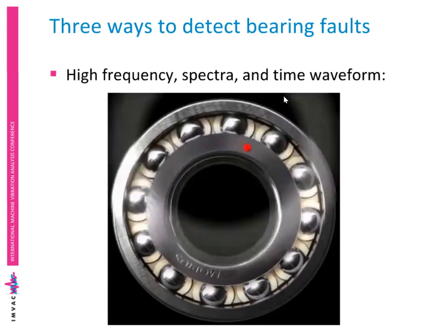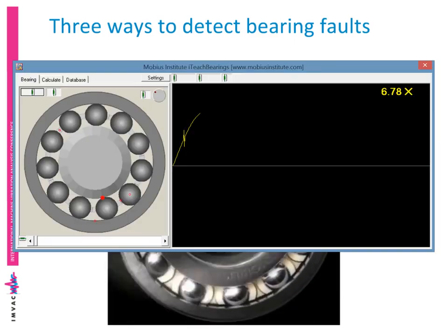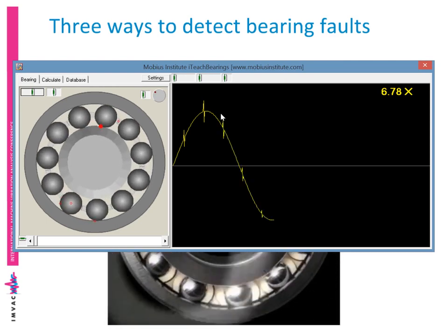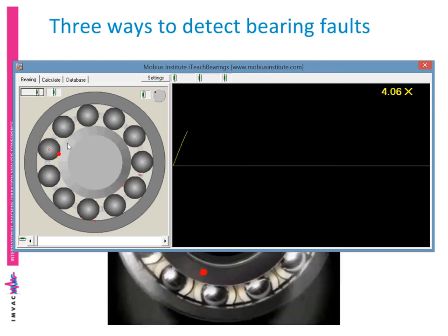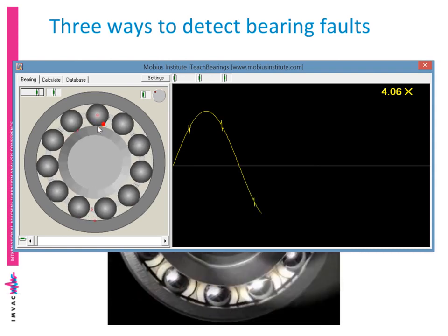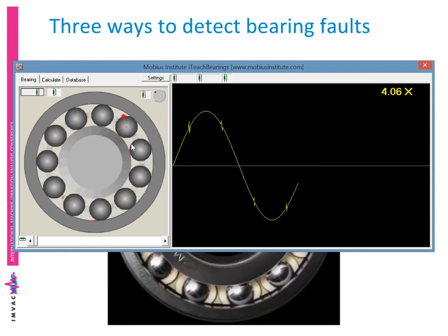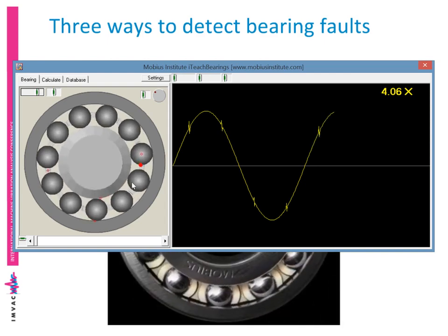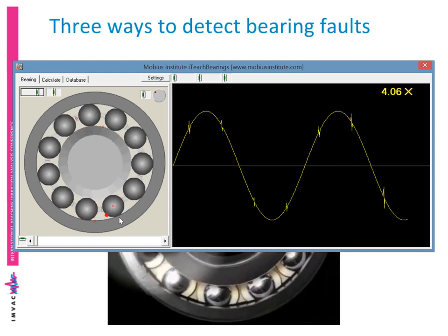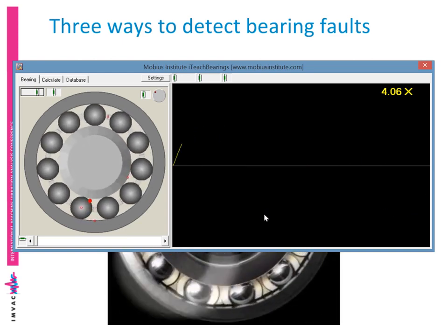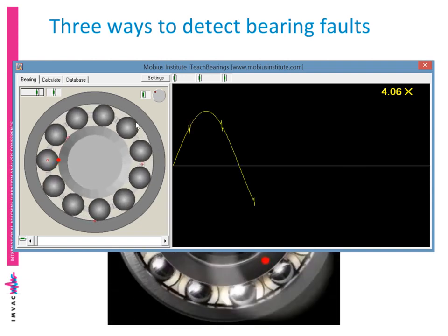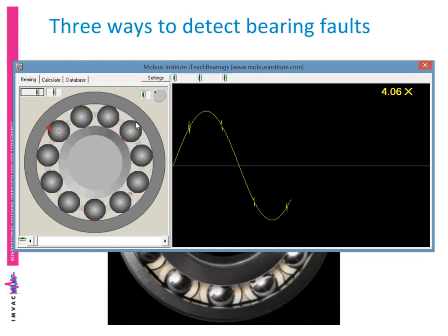But as the fault develops, we will also detect it as normal periodic vibration in a spectrum or a time waveform. So that's another sort of fault, and then if it was on the rolling element itself, then potentially 2 times per revolution of the rolling element, the damaged area will impact the inner race and outer race. Impact the inner race, then outer race, and we will see that in the time waveform as well. Now, if it's a ball and it's rolling along, it may be that it doesn't impact the raceway every time, or twice per revolution.